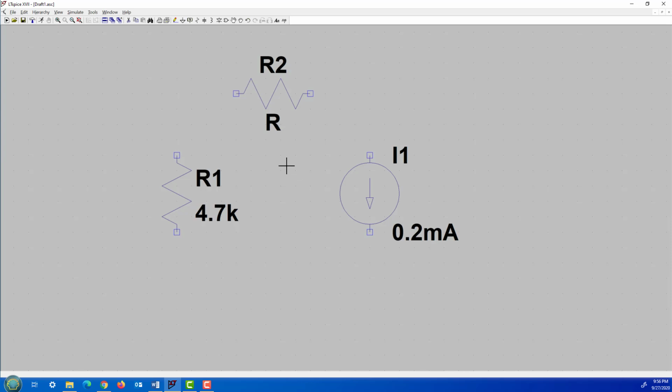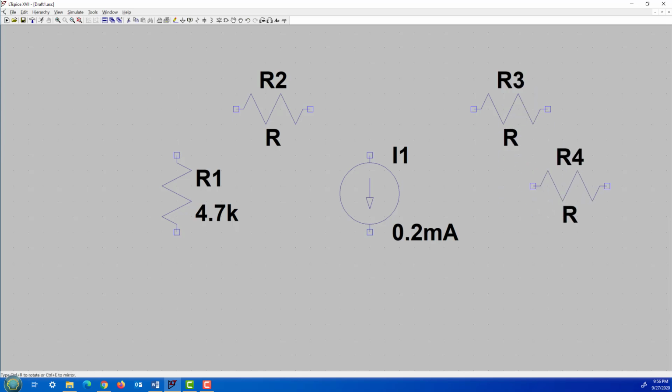Or maybe you want to do that, right? Let me go through and do that again. Okay, here's a resistor, right? Okay, let me rotate that. Control R, and I just put it down. And if I move it, there's another one here again, right? And then put that one down. If I'm done putting down resistors, I can stop here, or I can just keep going, right?